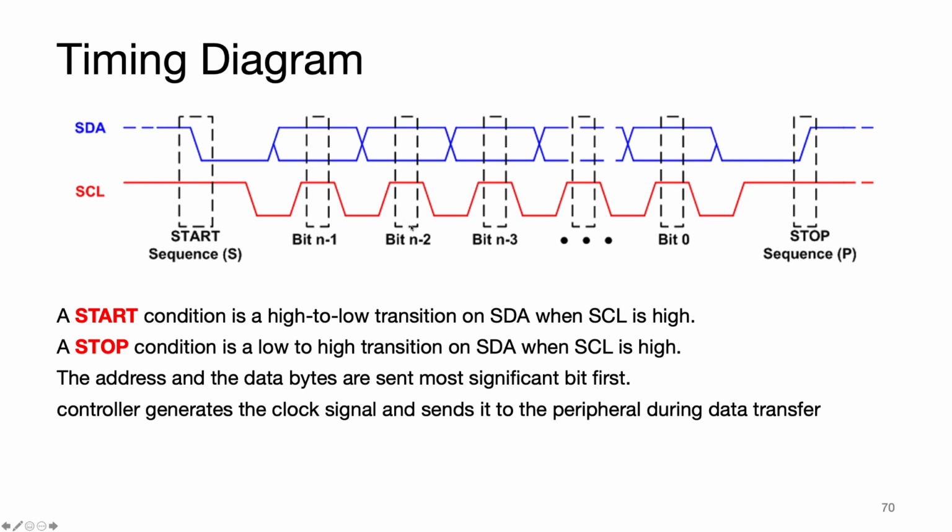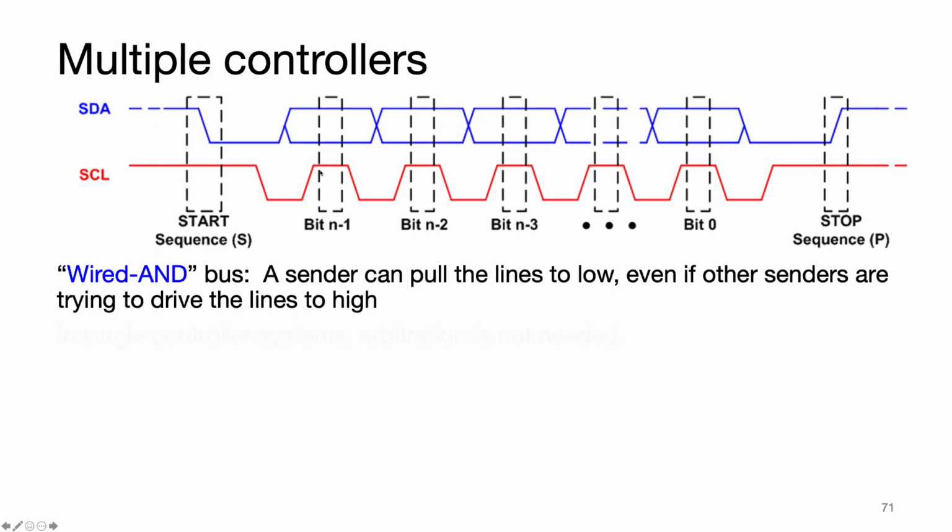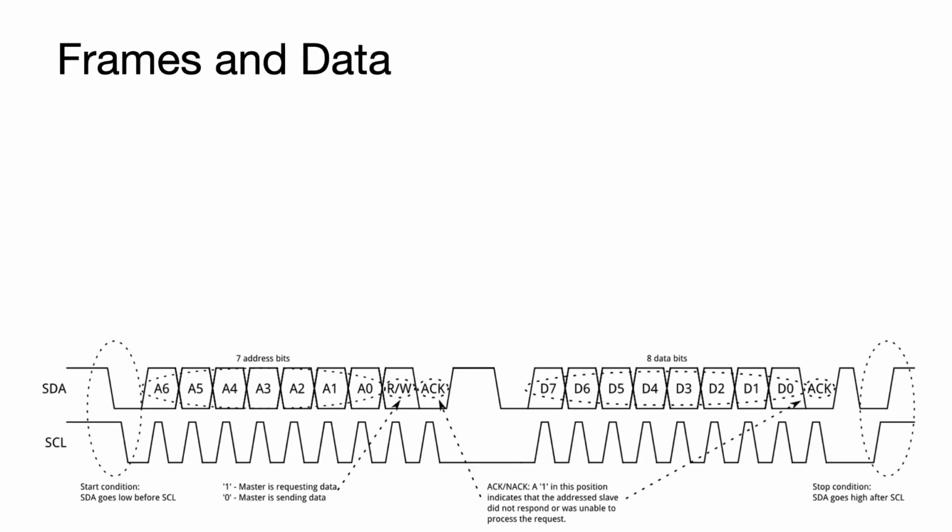Okay. Anyways, clock gets pulled, or data gets pulled low. Then there is some period to start a sequence. Then clock goes low, goes high, does its normal clock things while data is getting set up. So here's the setup period, and then clock is held high, and that's when data is latched into the peripheral. All right, let's look at what some data frames look like, because they're also a little interesting.